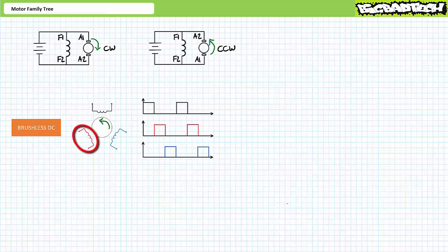Similarly, when field winding 2 is electrically excited by DC energy, it establishes an electromagnet which attracts the permanent magnet armature. Finally, when field winding 3 is electrically excited by DC energy, it establishes an electromagnet which attracts the permanent magnet armature. Successive time pulses to the field windings 1, 2, 3, 1, 2, 3 essentially create a rotating magnetic field, as would a 3-phase AC permanent magnet synchronous motor, only a brushless DC motor does so using DC.